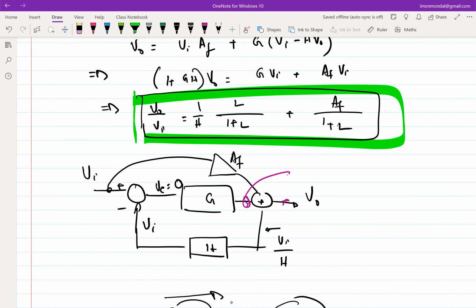Right. So in this case, the way the feedback system is drawn, there is a distinctive summation block, and we are doing Vi minus Vf. Okay? But if we think in the broader perspective of the negative feedback loop, the error voltage is the input of the error amplifier. Right? As I said, it need not necessarily be that Vi is applied at that particular location. I can apply Vi anywhere. I can break this G into two parts and apply Vi somewhere in between. Right? But as long as I can identify whatever is the main amplification block in the loop, all I have to do in my head is assume that the input to that amplification block will go to 0.